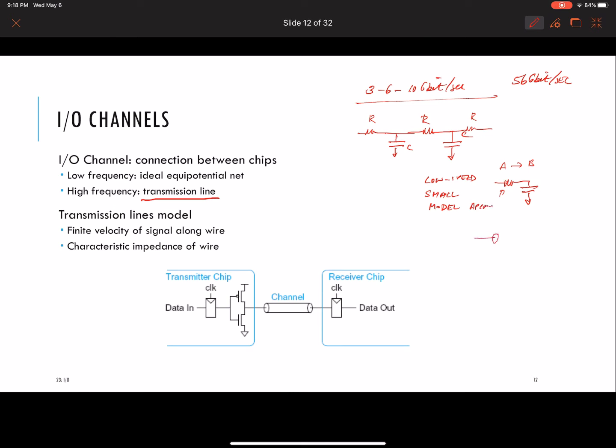And the next thing is like a transmission line. A transmission line looks like a fiber optic cable or an electrical transmission line: you launch something into it, and sometime later it shows up here. So you launch in time in, and sometime later, basically because of the flight time of this rising edge, this electromagnetic wave gets to the other side. So when things get longer and faster, you have your next level of abstraction, which is a transmission line. And then finally, once you get past that point, you can't use that approximation anymore. You've got to use Maxwell's equations.